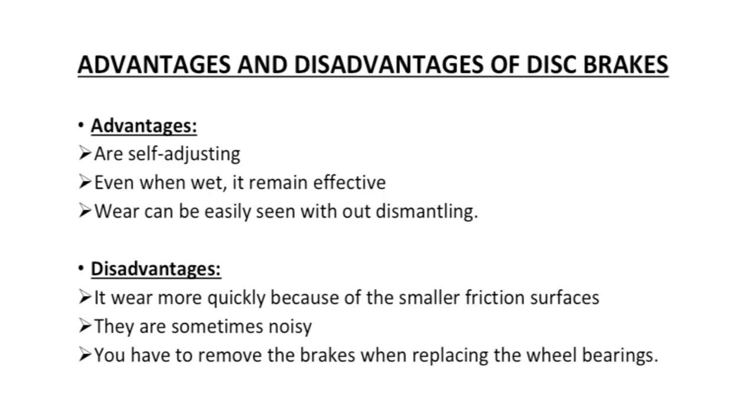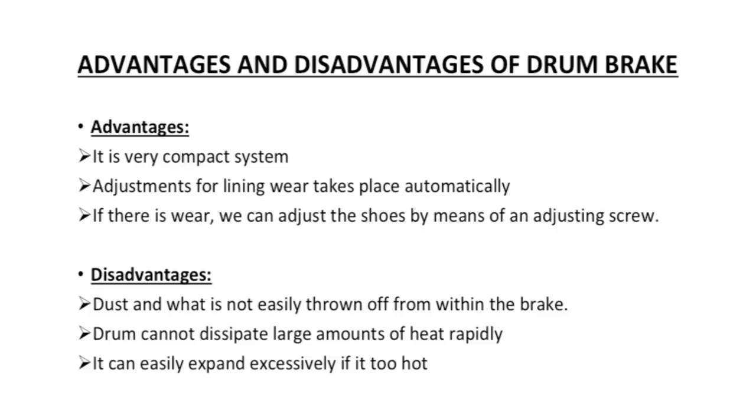Then the disadvantages of disc brakes: they wear more quickly because of the small friction surface. They are sometimes noisy, and you have to remove the brake when replacing the wheel bearing. So when you are replacing the wheel bearing on a car, the disadvantage of a disc brake is that you have to remove the whole brake system.